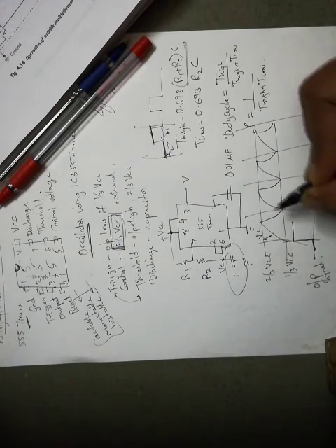So when we have signal above 1/3 VCC, the output signal starts rising. It keeps there until the capacitor reaches 2/3 voltage, which tells the signal to go low. Again at 1/3 VCC, go high, go low, high, low, high, low, and so on. So this is how we are going to generate the pulses. The very important part is how the capacitor charges and discharges. In the same way, the output signals are pulsated. So, a very interesting circuit.